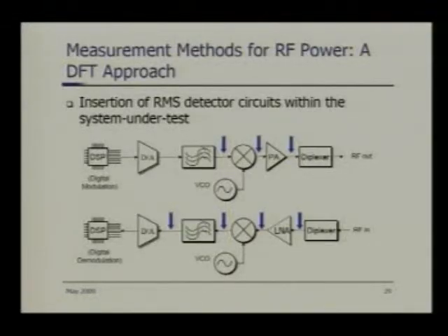Okay, so there are detectors like the peak detector. You see all of these, the RMS detector, the peak detector, that you have probably encountered in low speed analog circuitry. The only challenge is that in the case of RF circuitry, how do we achieve the same functionality for wide bandwidth and achieve a good dynamic range, because RF circuitry will not be very linear. So in that case, the peak detector or whatever the RMS detector that we design, we can plug in within the circuit itself.